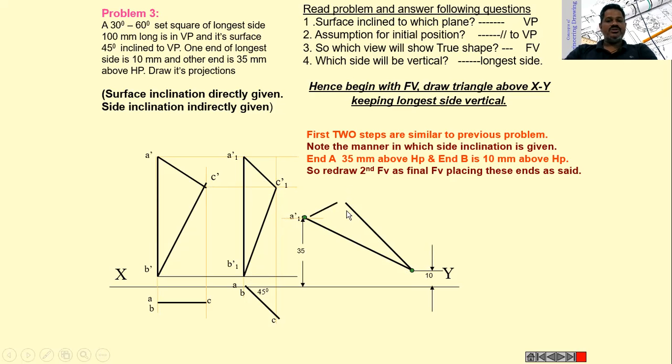Intersect the previous curve to get an intersection point here. Then join this point and name all those points as A dash, B dash and C dash. I repeat, to get the C1 dash point, take the compass with B1 dash, C1 dash as radius with B1 dash as center, and get the curve here.